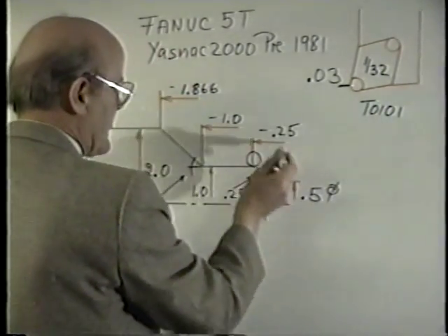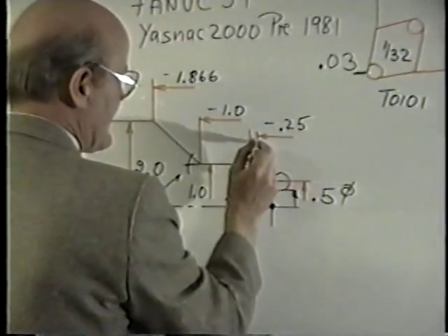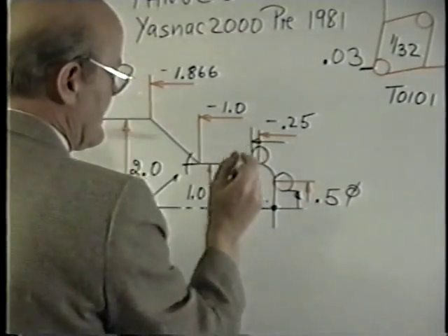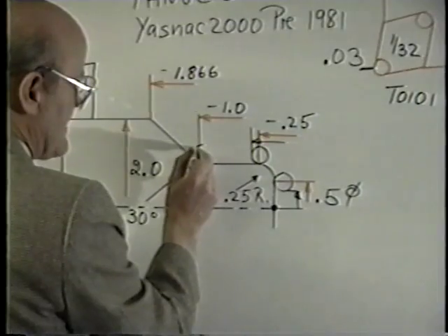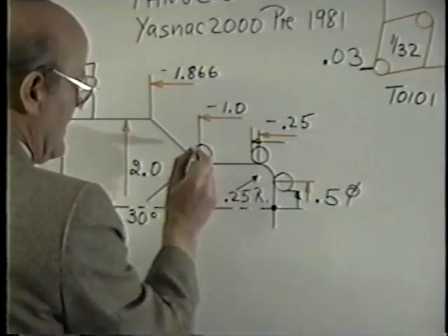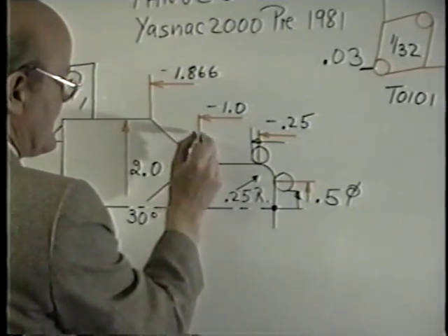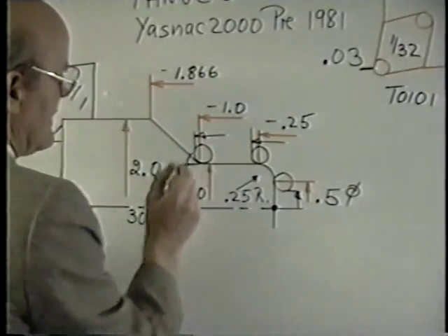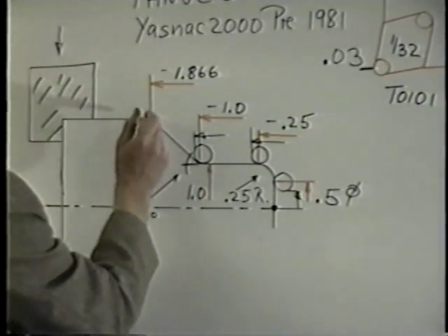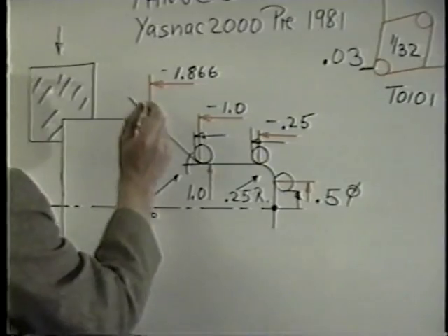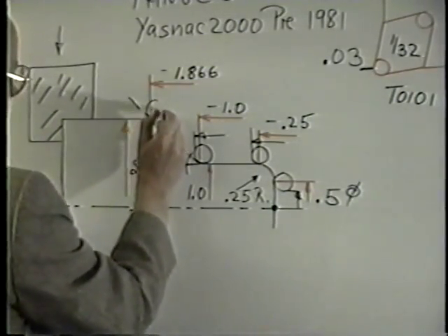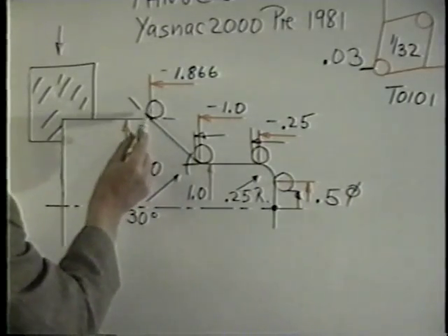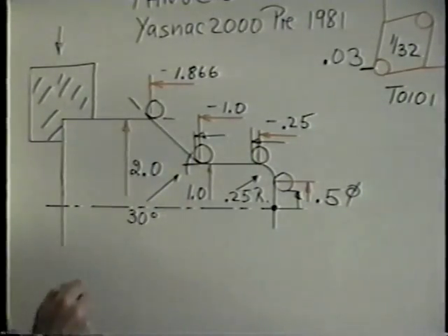And then as we swing around, we have to figure out an adjustment for this dimension. At this point, we have to figure out the tangent point between the tool and this angle. So there's an adjustment right here. And then as we cut up in this direction, we would have to extend this angle and figure out the tangent point where this ball meets the extension of this angle, and then we just go across.